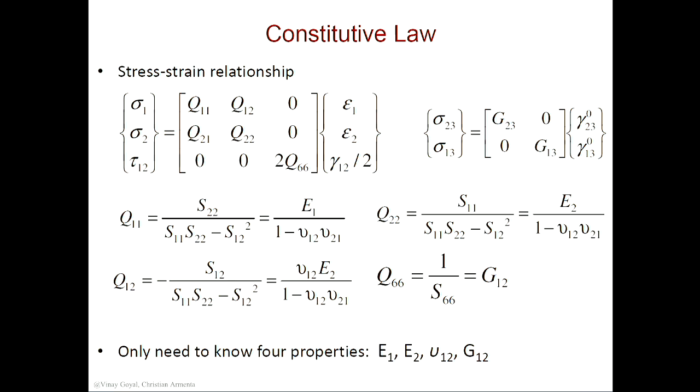And then what I can do now is construct my specimen, so there is a 90-degree specimen, so the fibers are perpendicular to the line of loading, and now I can get E22. And then from that way, you can actually get all the properties, okay? The G12 test, to get G12, you'll do a plus minus 45 off-axis test. That can give you G12 as well. So you take the plies, you put them plus minus 45, you test that, and you can get G12 if you strain gauge that correctly.